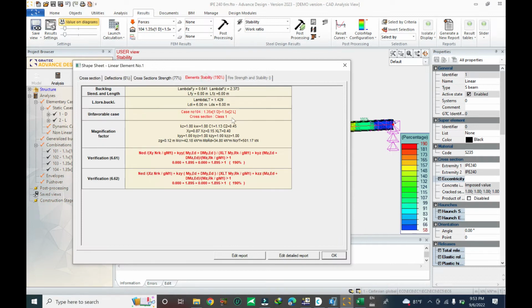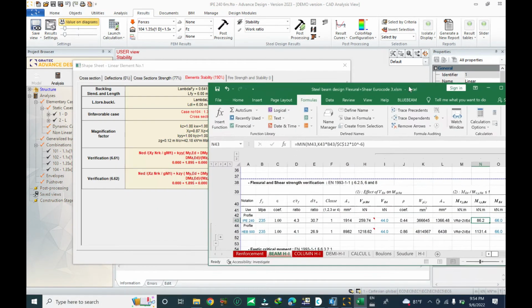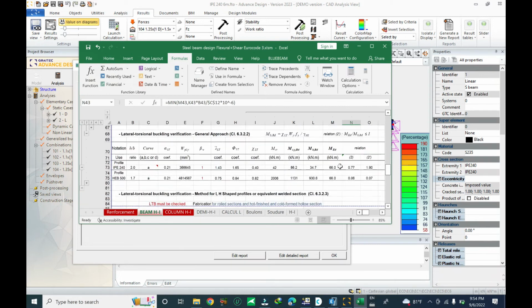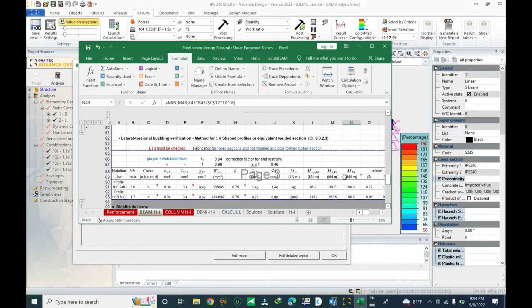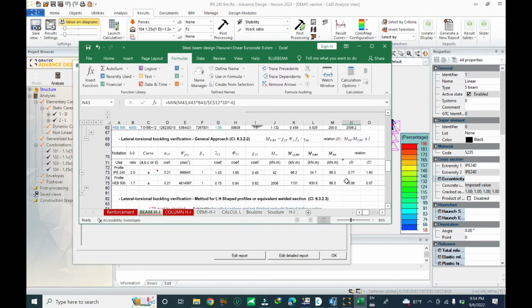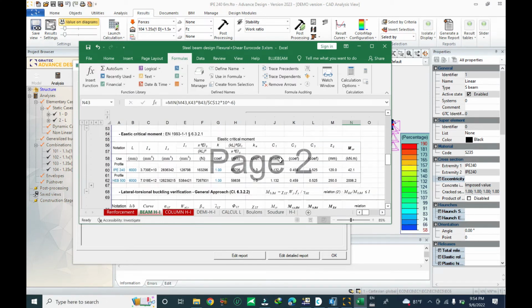Now let's check the stability and design load case control. This beam is ultimate load combination, and SY is 6. Yeah, it's correct. For the buckling and for lateral torsional buckling, yeah, it's correct. 6 meter. And the KZ is equal 1, KW is equal 1, C1 is equal to 1.13. Yeah, now let me check the parameter of C1. Where is C1? Yes, this one. You see here the parameter is 1.13.